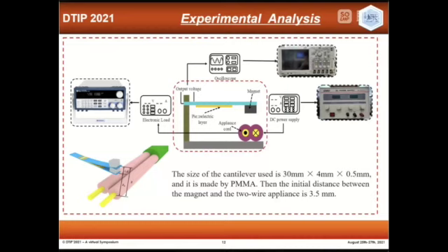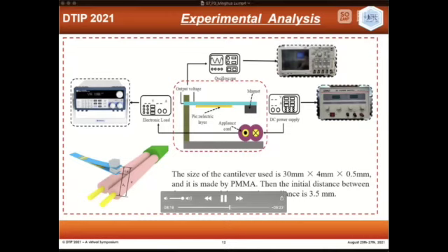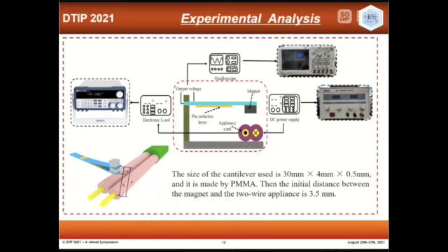The calculated results are shown in the figure, and the graph includes the comparison between the theoretical results and the experimental results. It shows that whether the current is turned on or off, the output voltage always has a growing trend with the increasing number of magnets.